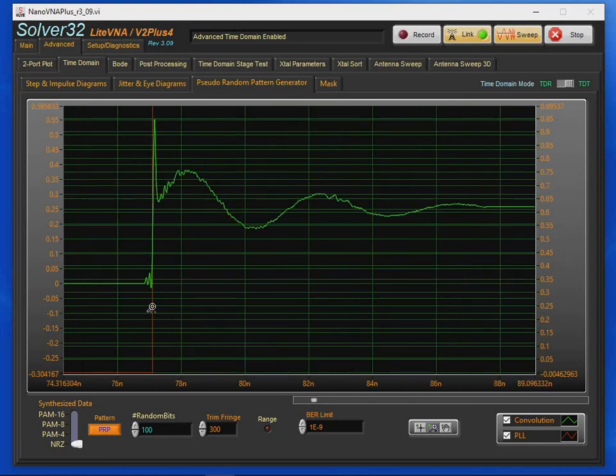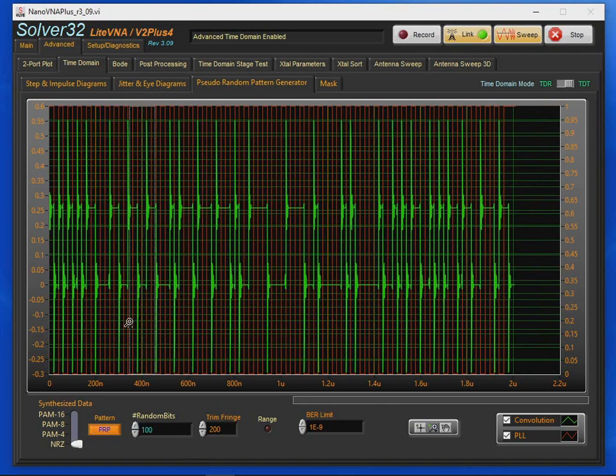And you can see we're at 77 where we start. And that first dip is at 80, so 3 nanoseconds over for the first dip. The second one is at like 85-ish nanoseconds out. And then the next dip would be probably about 89 nanoseconds out. So very close to what we're seeing with the oscilloscope. This is looking at our falling edge. Again, the two should be basically the same.